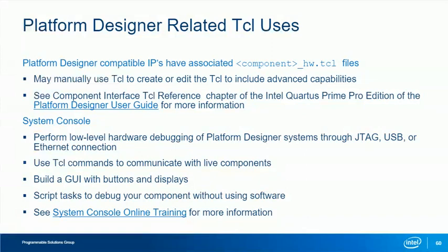Usually, for a custom component, this Tcl file is automatically generated by the component editor. However, if you want, you can further customize your component by hand editing the Tcl file to include advanced capabilities such as HDL generation using instantiation parameters of the component. Please see our component interface Tcl reference for more information.